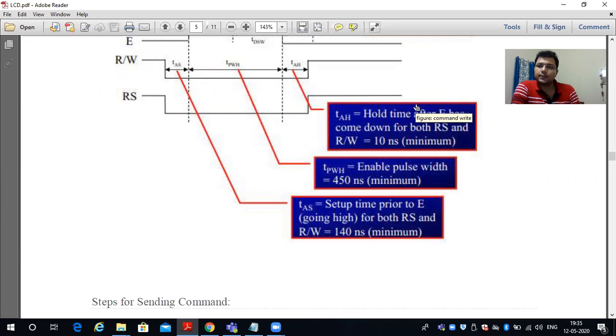So initially we will send the higher nibble, the higher 4 bits, and then subsequently the lower 4 bits. So it requires 2 times to send the data, which will then find its position in the data register and subsequently be displayed over the display unit. When enable goes 1 for a while and then goes 0, before that, read write should be 0.